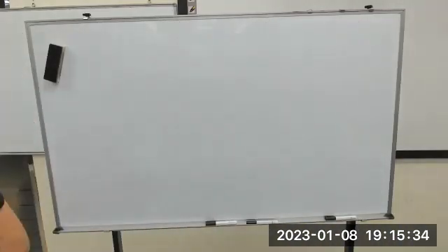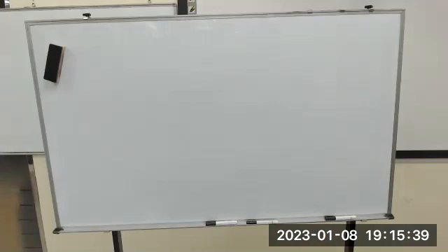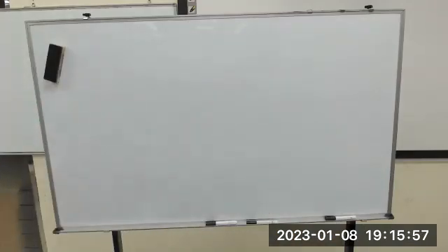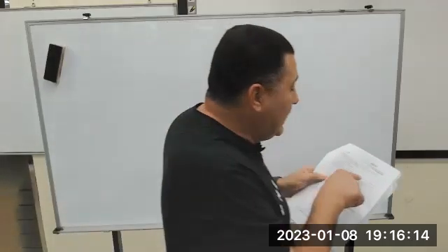Now we have shear, moment and normal force. They develop what? No, they develop stresses. This is what the internal forces do: they develop stresses, and these stresses are what we need to design for. Correct or not? We need to design for sure, 100%. Once we define the stress on a structural element or section, we can design this section. Correct? And load balance is one of the key considerations in structural design.